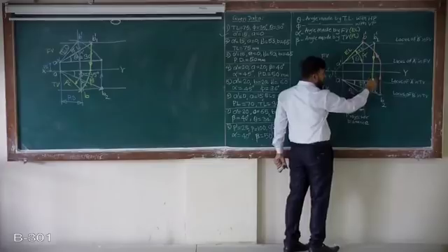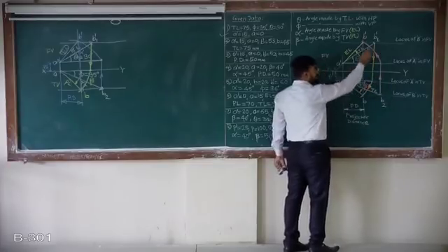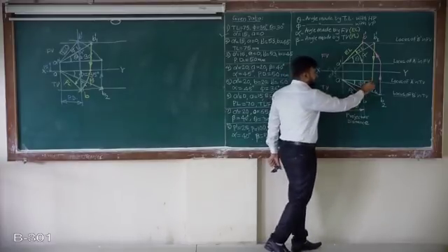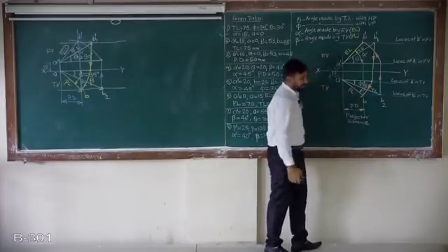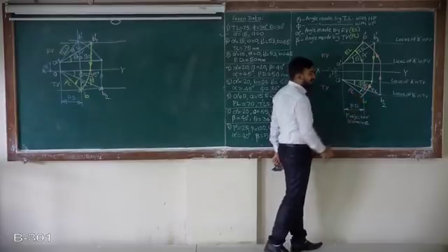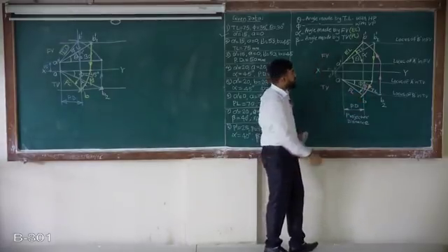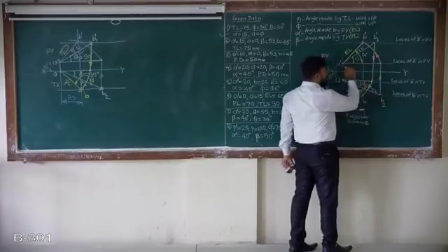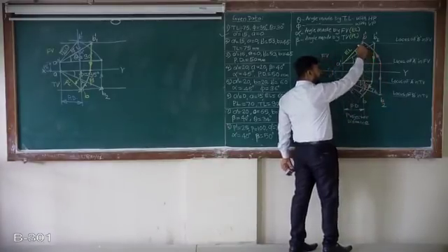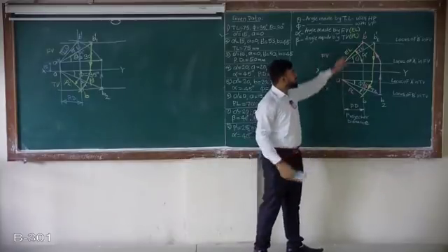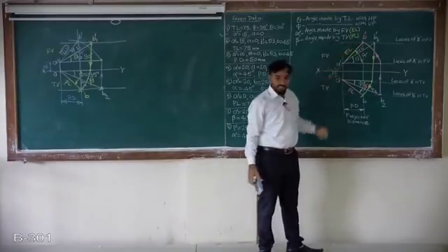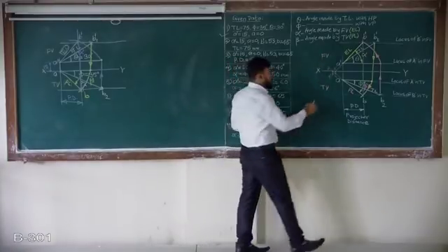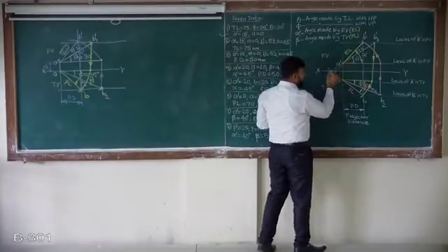EL and PL, how do we get EL and PL? Project B1 dash onto the locus of A. So from this I have drawn one projector or perpendicular. Then rotate onto the locus of B. So that is your PL, angle is beta. So that is the complete top view. Same for EL. Project B2 as a perpendicular onto the locus of A dash. Again rotate, you will get point B dash and the length is EL. So complete front view.